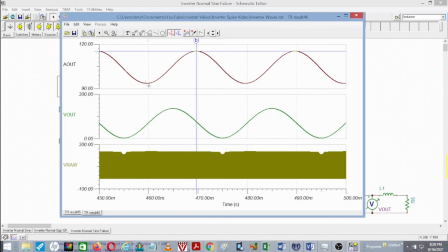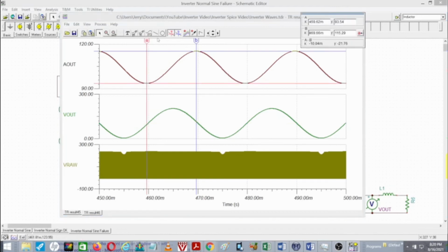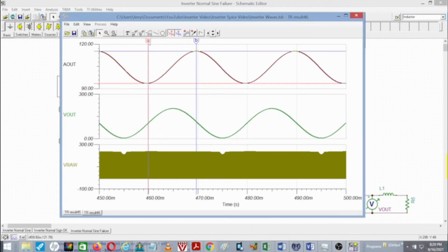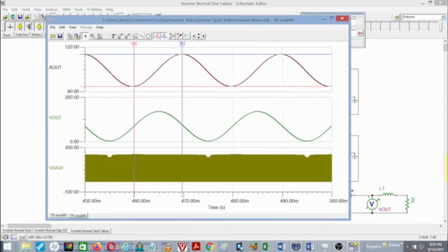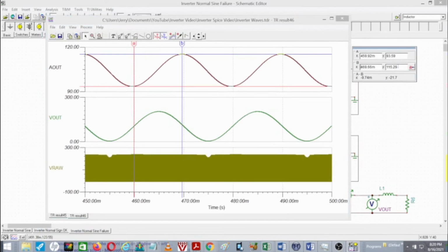But what's even more interesting, even when the AC voltage is at 0, we have almost, and where did my little results go? They went here. We have almost 93 amps of current flowing at the negative excursion of the sine wave current, and at the positive excursion of current, 115 amps in a load that normally pulled plus or minus 30 amps.